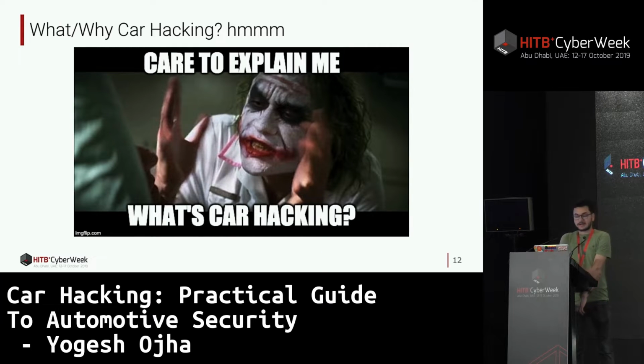Now let's talk about car hacking. As automobile networks are increasingly getting complex, they're running millions of lines of code. They've got hundreds of ECUs and hundreds of sensors, yet they employ the decades-old CAN bus protocol, with little or no security. Furthermore, the tools needed to access the CAN bus are widely available at very little or no cost. There are many software tools available for free for everybody to use. And as I said, the underlying communication system is a CAN bus, a controller area network that has remained unchanged for many years.